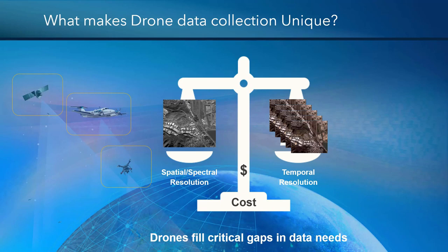They do have good spectral resolution though, meaning they have infrared, they have thermal in some instances, and far infrared. Aerial photography is also good because we can get good resolution, 5 centimetre resolution imagery, and we can get that on regular flyovers, so half yearly, yearly sort of flyovers. The issue with aerial photography, though, is that it is expensive to run, and so generally we fly very large areas. So drones, though, they fit in that niche area where we want high temporal resolution, so I can fly every day, every week if I require, and they give me a really good spatial resolution as well.